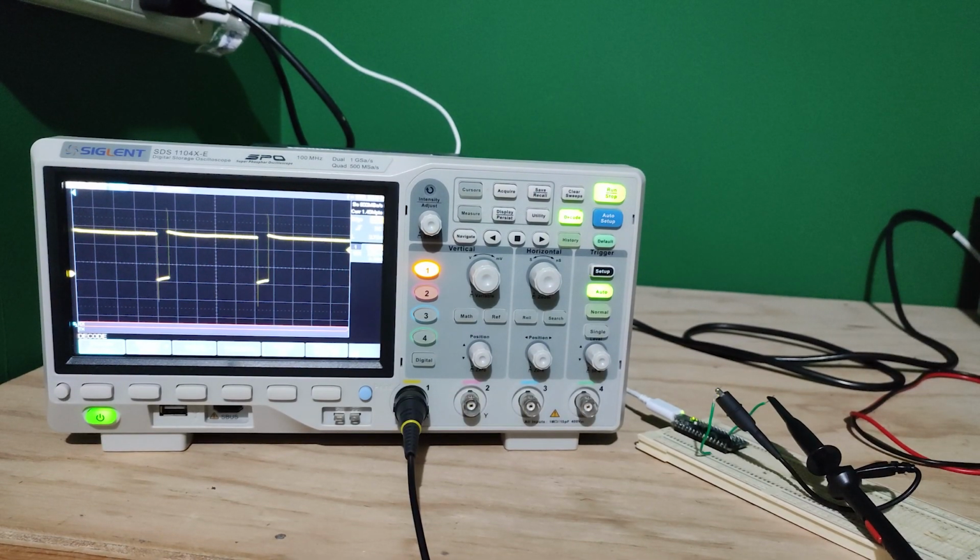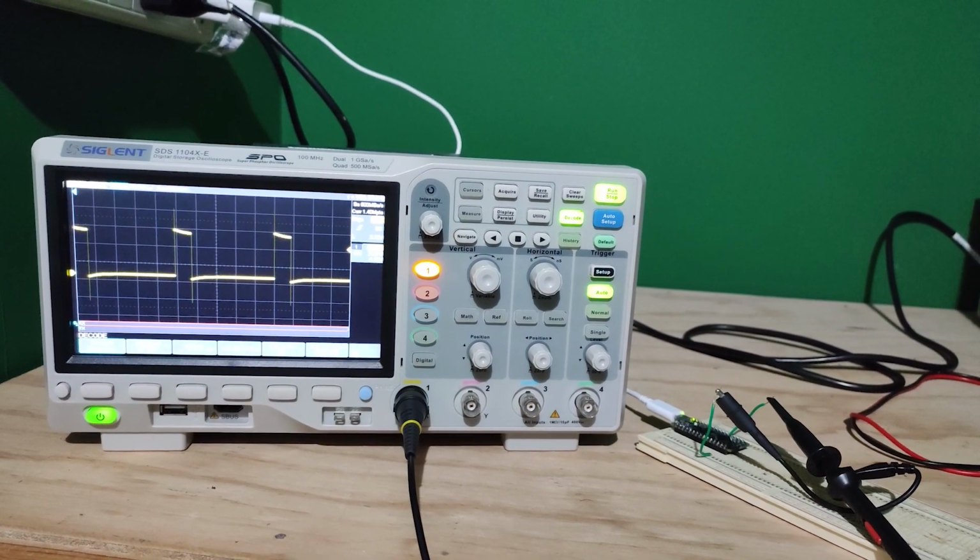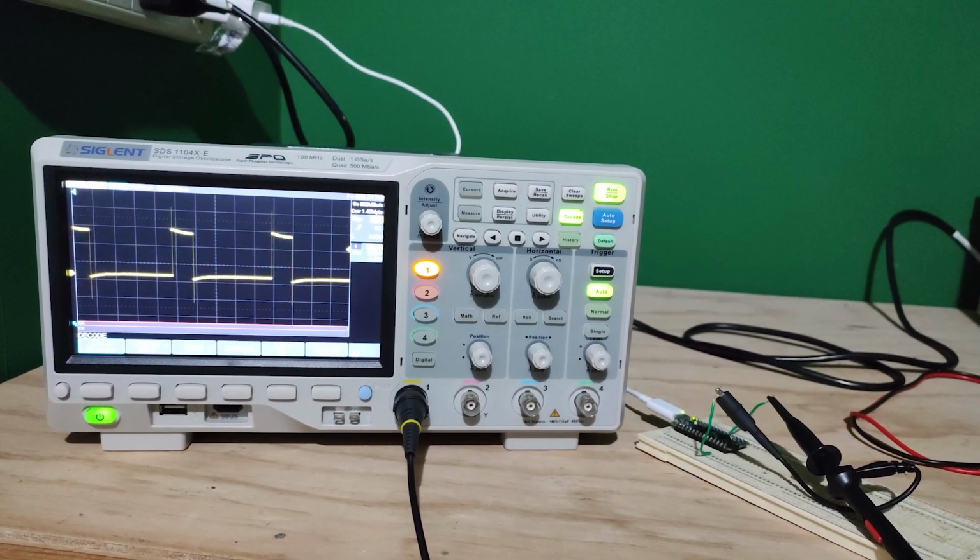So here we have the PWM being generated by a digital method, which is the ATmega microcontroller. I made a code to keep increasing the duty cycle until it reaches the maximum and goes to the lower again. We can see that we have a more stable and better looking signal, or at least a signal that is more proper to many cases where PWM is required. This is a very simple code to generate, but we can apply it to many cases to find many useful applications. So PWM is best applied when it's generated by a digital method.